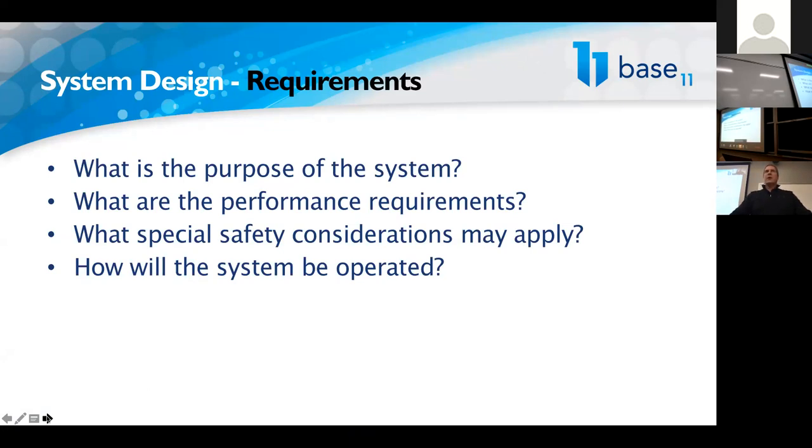As we've talked about, you're going to have an overall system and you're going to have subsystems. For example, if you're burning liquid oxygen in your rocket, you may have a ground support system that involves how you manage getting LOX from the ground support successfully into your rocket at the conditions that you're going to need. We're going to talk about the performance requirements: what are the pressures, temperatures, flow rates, safety considerations, all of those types of things.